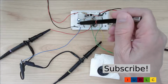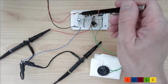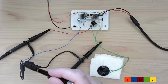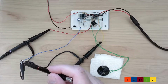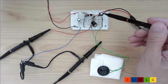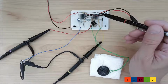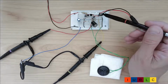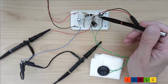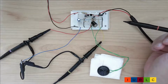We have a single voltage supply, 0 volt, 5 volt, the supporting capacitor. The 0 volt line goes here to the ground line of the oscilloscope probes, to the loudspeaker, and here to the signal generator. The signal from the signal generator has now an offset of 2.5 volt to be in the middle of the 5 volt supply, and it goes here to the two input transistor bases.